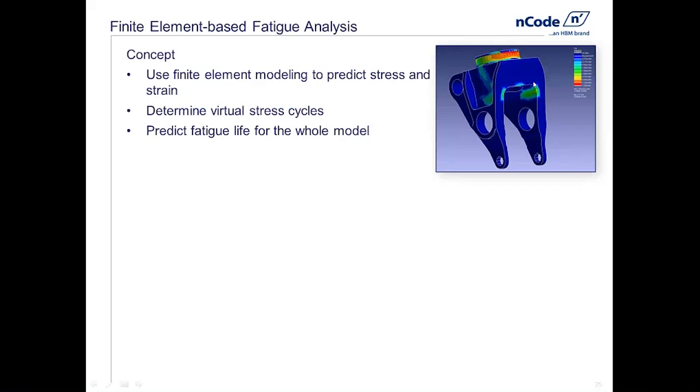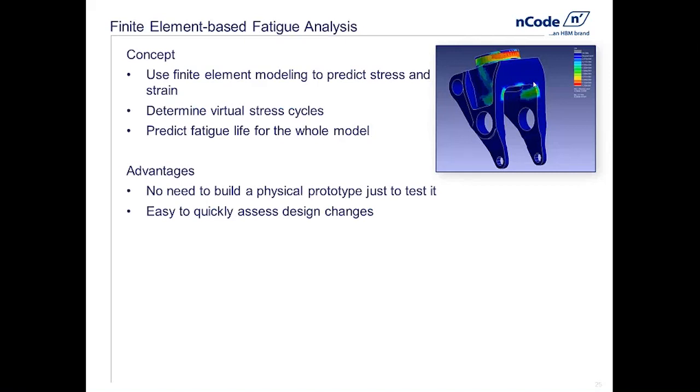This is not stress in the typical FEM sense. Now this is actually fatigue post-process to get into life. How many cycles, how many hours, how many landings until failure. So the advantage of doing this is that we don't have to build something just to test it. This is what chances are your senior management in your company wants you to do. Get away from physical prototypes. Certainly the board of directors and investors in the company want everybody to do this because of cost and timing reasons. It's very easy then to assess design changes.